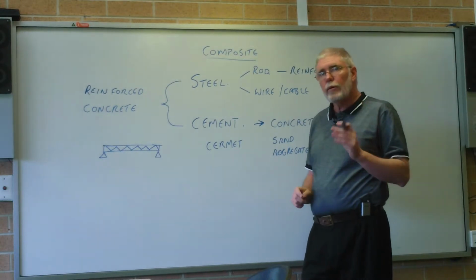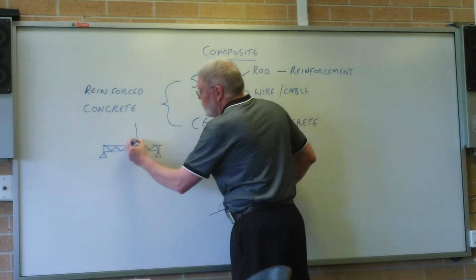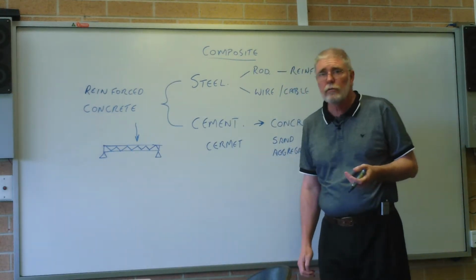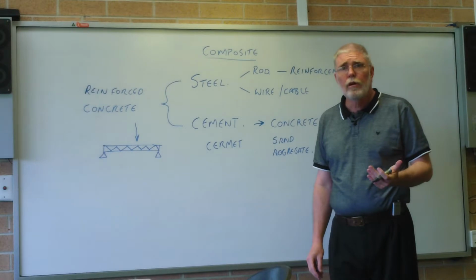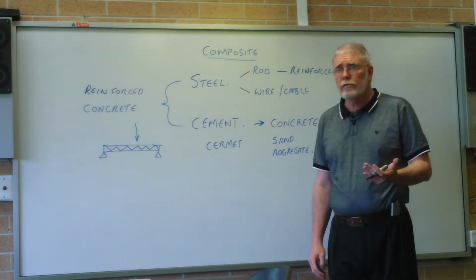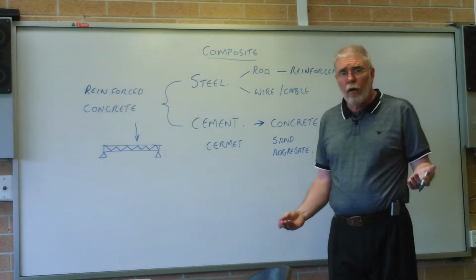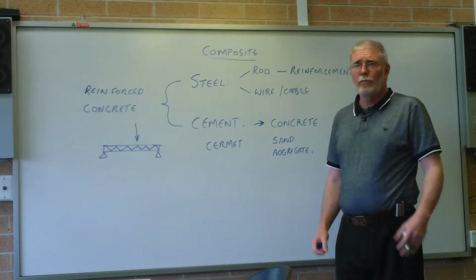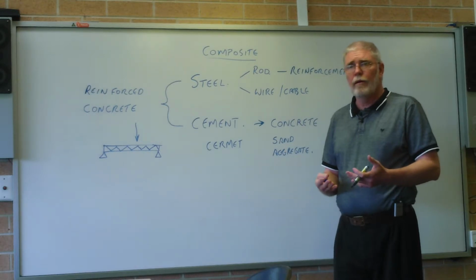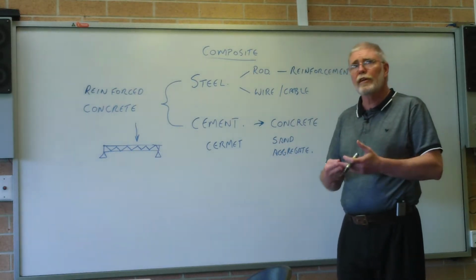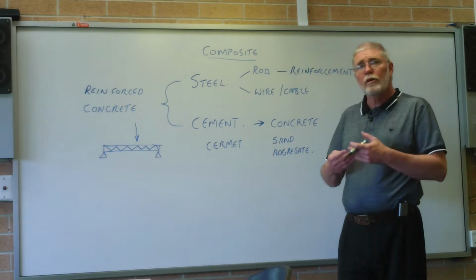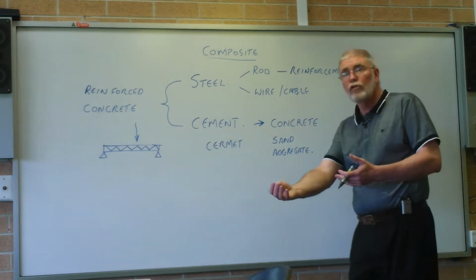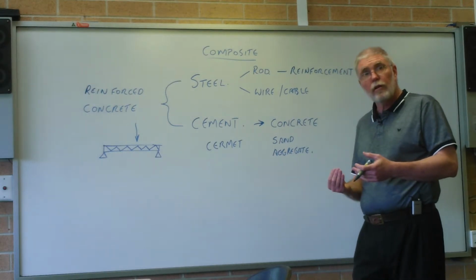But here's the big deal. The problem is when we load it, we're going to have deformation. Why do we have deformation? We have to have deformation. Without deformation, you don't get resistance. If you don't get resistance, it doesn't hold the load, in which case it's a very useless piece of material as a beam. We don't want it to break, we want it to bend. And the more it bends, the less likely it is to be useful either. So we want it to have some stiffness, which is good, but we also need it to deform, to get that reaction that'll hold the load.